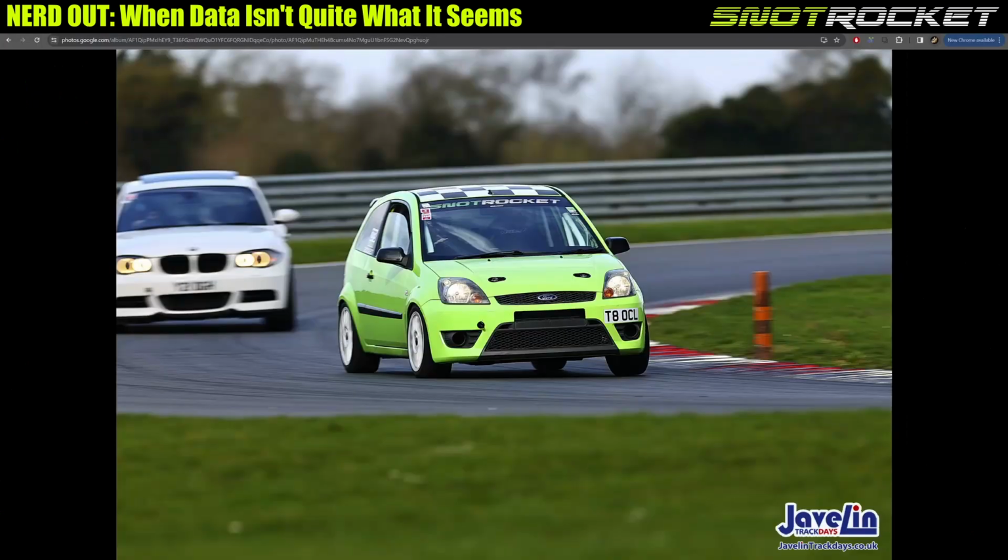Just going back quickly to give you some background. The car used to have the original Honda OEM heat exchanger that goes between the oil and the water, so that the engine coolant heats up the engine oil quicker, which is good from a wear and emissions perspective. And then once everything's up to operating temperature, oil and water around 100 degrees, they help normalize the temperatures between themselves. But it's a really small heat exchanger. It's not designed for heavy sustained track use, and it's mostly for emissions and engine wear.